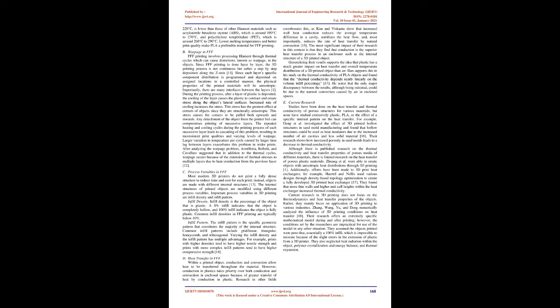Process variables in FFF. Most modern 3D printers do not print a fully dense structure to reduce time and cost for each print. Instead, objects are made with different internal structures. The internal structures of printed objects are modified using different process variables. Important process variables in 3D printing are infill density and infill pattern.